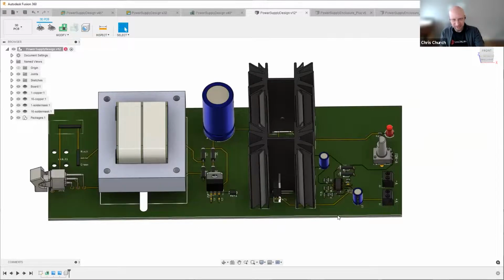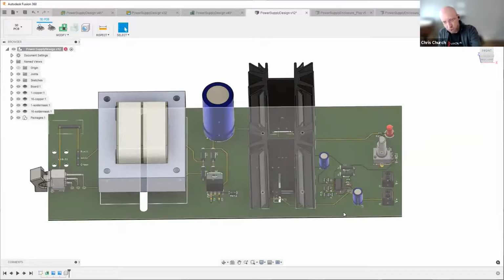On this AC side, again, I don't know how much current this thing's going to be running through, but our engineers will size those test points with you to make sure we can put the appropriate amount of power through an analog power circuit like this. So they'll probably be larger on that AC side and slightly smaller on the DC side, just to make sure that we have enough there.